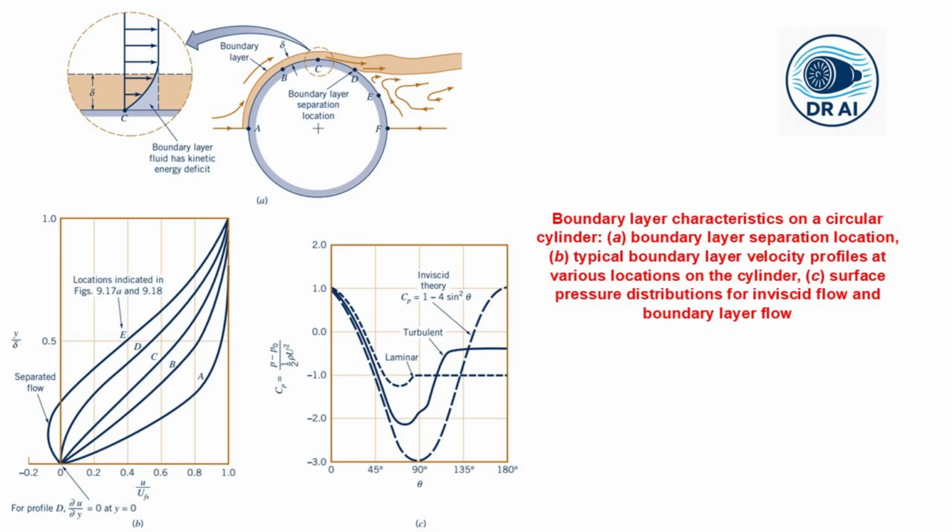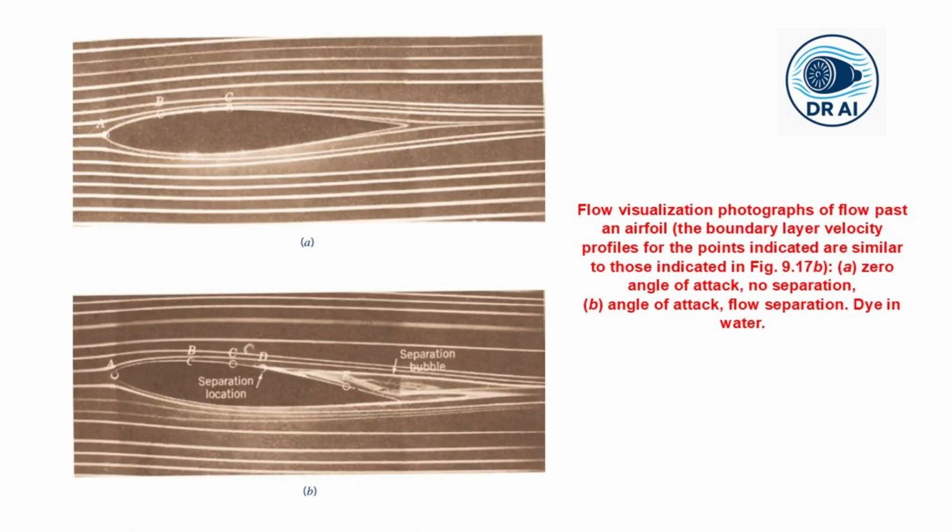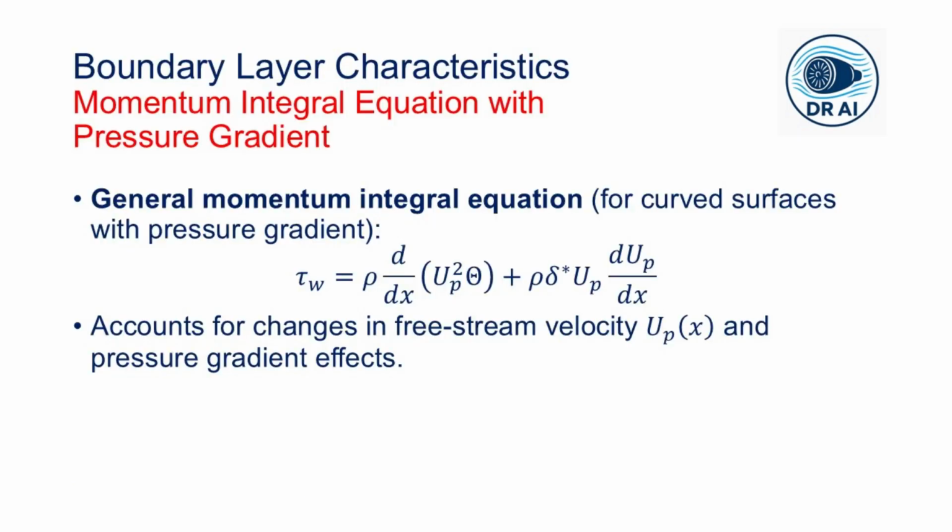The dimples trip the boundary layer to turbulent at a lower Reynolds number, reducing the drag and allowing the ball to travel farther. The same principle applies to airplane wings. At high angle of attack, turbulent boundary layers delay the stall process, allowing higher lift before separation.